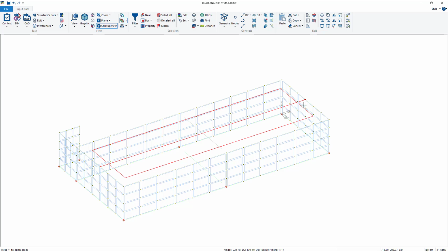Okay, now you see that this midline in the floor indicates which direction the floor is, basically in which elements it distributes its weight. So in this case it's on this wall and this opposite wall. But we have only one line. It means that the only nodes that take the load are the external ones.